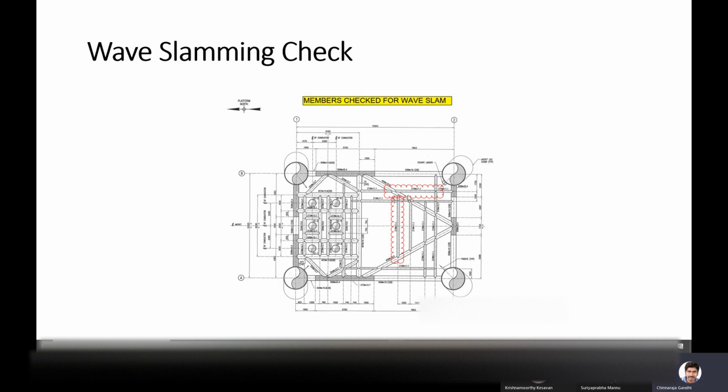Okay. Now the second question is whether I have to check this member or not. We have to identify that, and here we have to use our engineering judgment. This is the member which is 219 diameter with 11.1 thickness. Out of these, this is the least member diameter, and it has the longer span in this framing elevation. If you take and check this one, and if it passes, then it will be sufficient for all the members; they will pass.